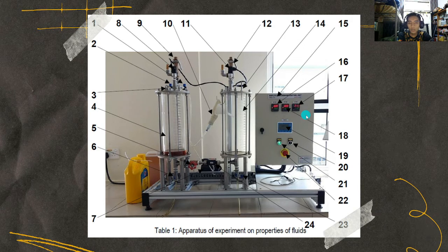After that, we will repeat steps 5 and 6 for 2700 milliliters, 2800 milliliters, 3000 and 3100 milliliters, and lastly 3200 milliliters. And then we will record all the pressure and volume measurements accordingly, and we will perform the shutdown procedure.